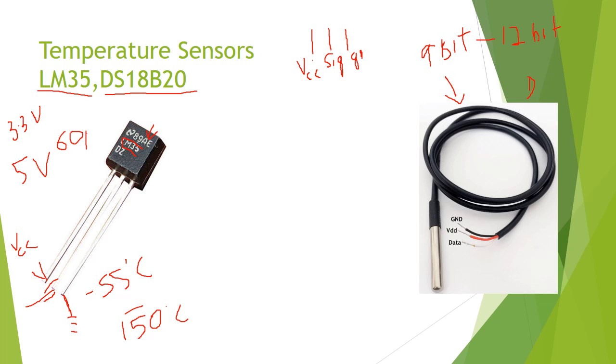It's very minimal from an electrical point of view. It can go into milliamps, but it will never go above 1 milliamp, because it will lead to destruction of this temperature sensor.